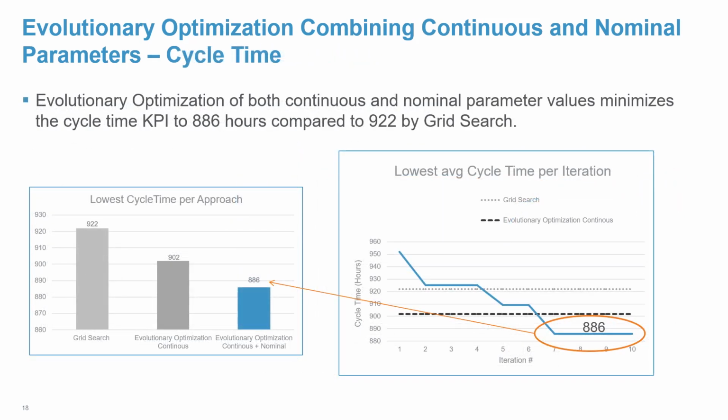The same thing happened with cycle time. Here again, we jointly optimized the line balance parameters and the bottleneck stations using evolutionary optimization while measuring the average cycle time KPI. In this figure, we can see that the best cycle time in each iteration goes down. Each iteration is 20 runs. And in each run, we vary both the line balance parameters and the combination of bottleneck station families.